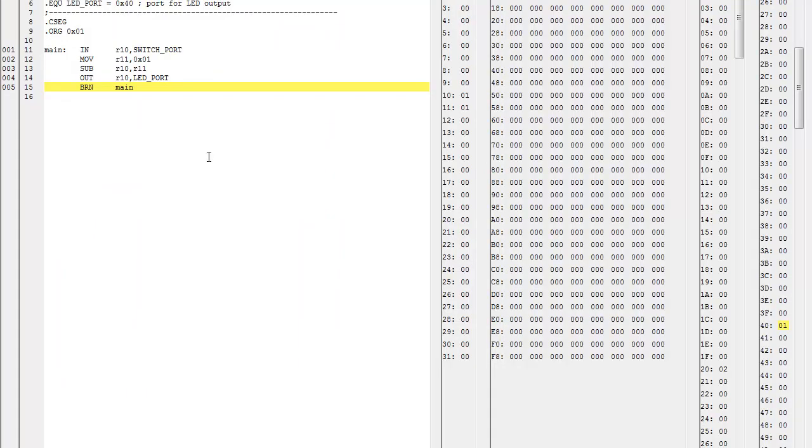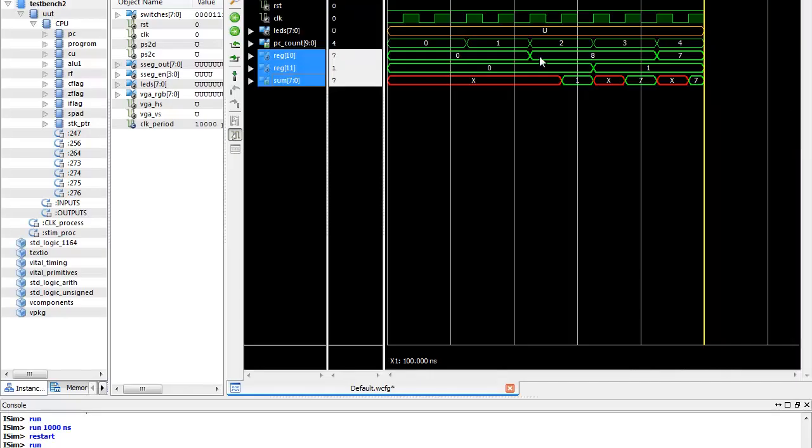Even though we only had 4 instructions, since I started my counter at 0, it had to run that 0th instruction, which did nothing because there's nothing there, and that's why it took an extra 2 clock cycles to get us to 10. My counter started at 0 because in my code I had set the counter to 0 initially, but I advised you to set it to 1 initially so you don't have that extra clock cycle.